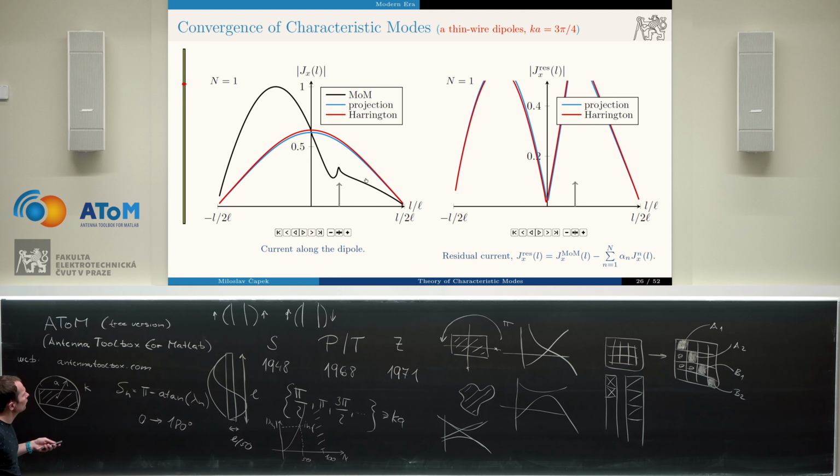Here are the characteristic numbers, lambda 1, 2, 3. For the bow tie, we have more of them. We have 4. And you can see, once again, where they resonate, so where they cross 0 of the eigennumber, how the current looks close to these points, and the same for the bow tie. And now we can evaluate Q, knowing how to do it.